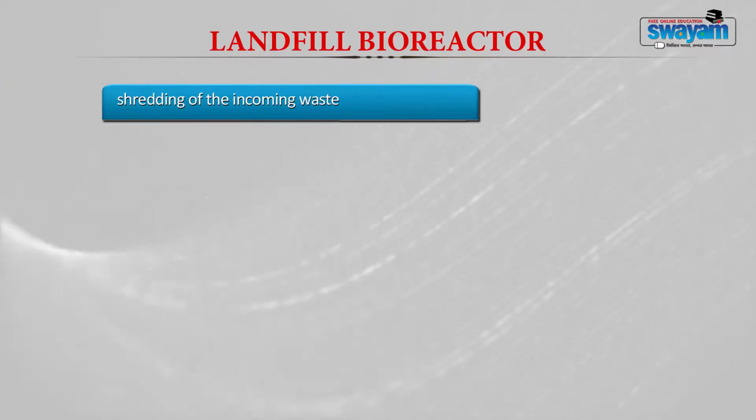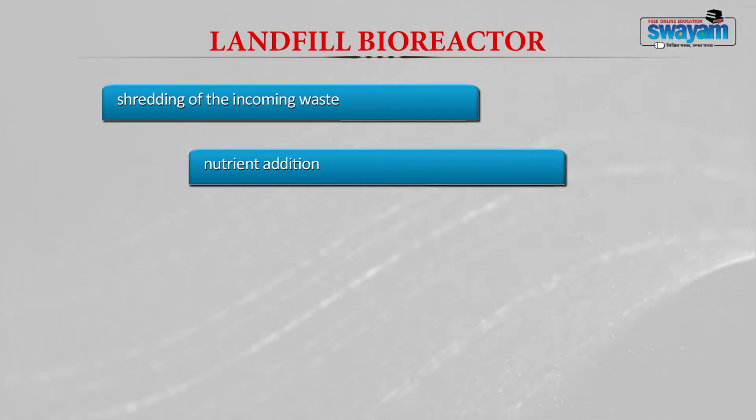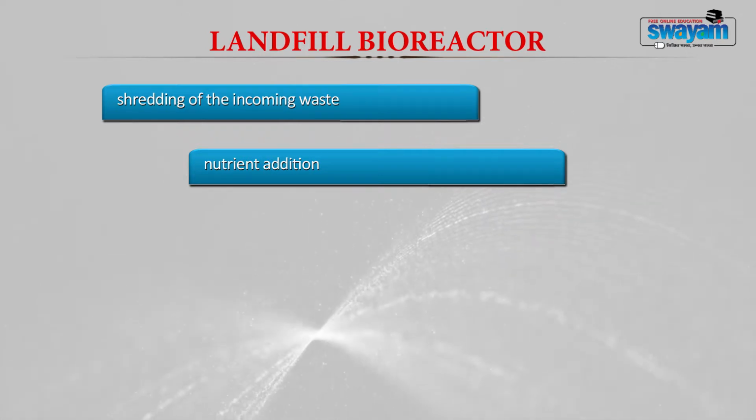The efficiency of a landfill bioreactor is increased by certain factors. For example, if the waste being loaded is shredded into uniform size, that will accelerate the rate of degradation. So, shredding of incoming waste is one factor. The other one is nutrient addition. Sometimes the rate of degradation is limited due to the absence of certain nutrients like nitrogen.